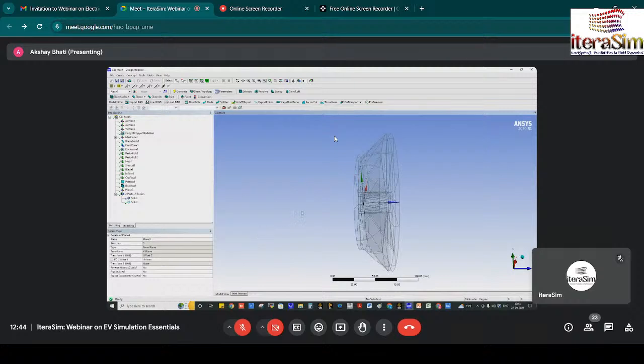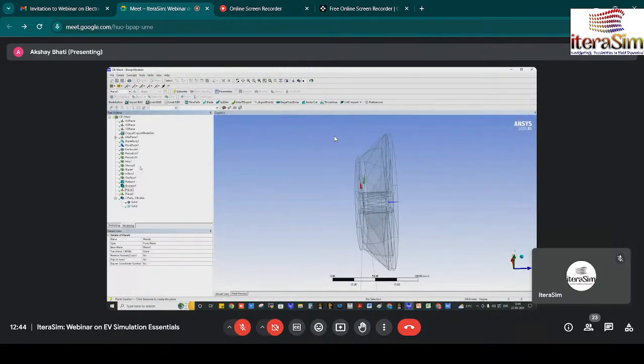Another one we want to separate is at the leading edge of the part. So we will create another plane, from plane XY only, because it's the origin, so it is easy to take the dimension. It's a 40 offset along the Z axis, because Z is the axial axis, in which we will take 14 mm. So here you can generate a plane over here.